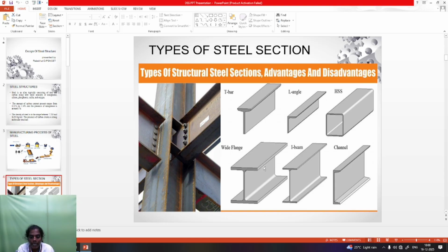Next, Indian Standard Heavy, meaning a heavy load and weight, defines a heavy beam structure. Light means the weight is very low, a light beam. ISLB, ISHB, ISWB: these are the different categories of the I section.